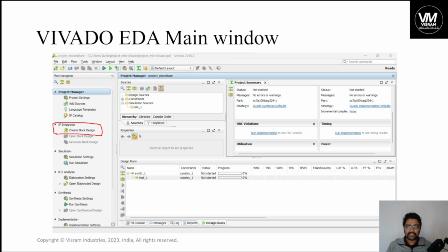This intellectual property called the microblaze processor is already developed by some vendors in the industry, and now we are taking it and specifying our own specifications on the IP, and by our own specifications we are generating the VHDL out of it, so that VHDL we are using to convert into bit streams, and we can use it for simulation purposes as well.